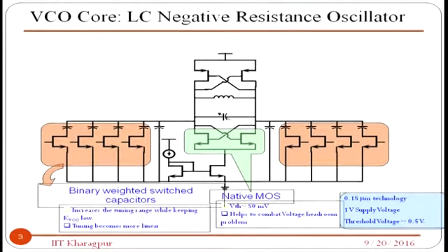So I can use those switches to go from say 2.4 to 2.45, then 2.5, 2.55 like that, by those coarse tunings. By those capacitances I can select the band starting from 2.4, then 2.405, then 2.41, so 5 megahertz spacing.